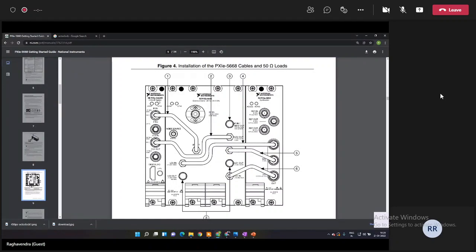What the 5624 does is, it takes in the analog input, it has ADCs inside it. It takes the analog input, gives it to its own ADC, and then it gives out that value as a digitized value. You will actually get a digital signal from this, which, similar to USRP, you can take onto your system and then do whatever signal processing you want.